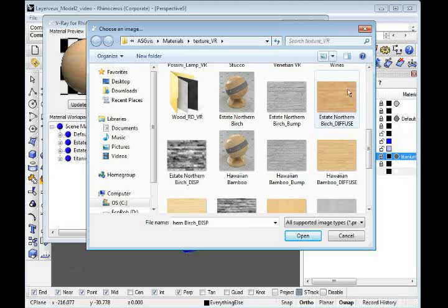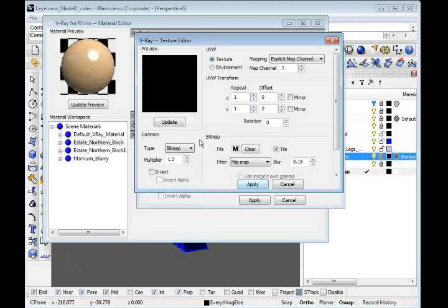So this is the original material that I had, brought it into Photoshop, I turned that into grayscale, I inverted that, and this is what I get. It looks like a negative. Then I took this image, and again in Photoshop, I changed some settings to turn this into more of a bump. If you want to know more about bumps, I will have another video set up for creating a bump in Photoshop, so that's much later. In most cases, the material has three images: the raw image, the inverted image, and the bump image. Simply hit OK, apply it to that, and hit update, and you'll see that there.